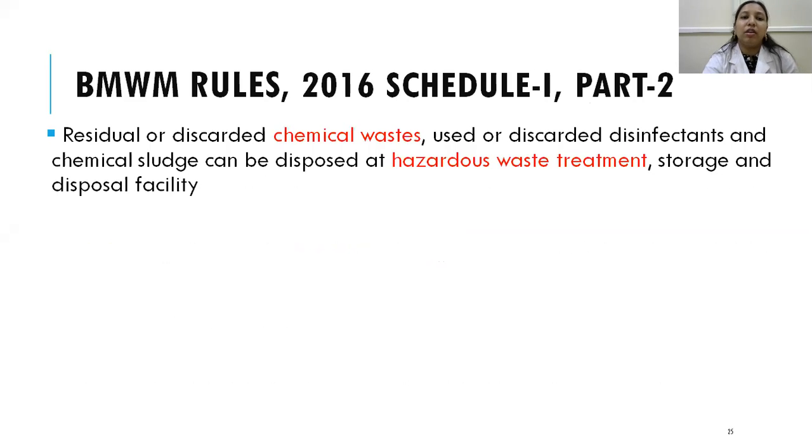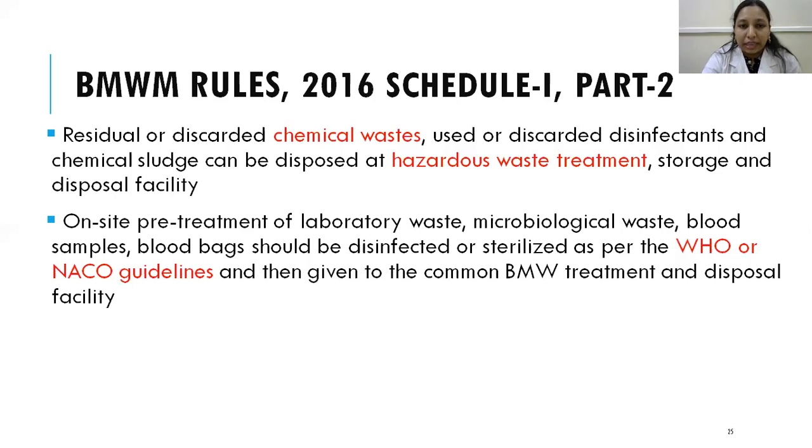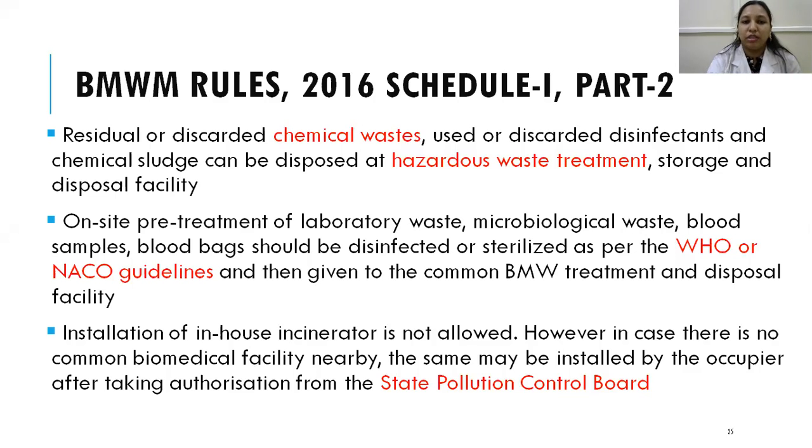The residual of discarded chemical waste, that is the disinfectants and the chemical sludge, can be disposed of at a hazardous waste management facility. On-site pre-treatment of laboratory microbiological waste should be done with disinfection as per WHO or NACO. What is NACO? National AIDS Control Organization. According to those guidelines, we have to pre-treat it, and then send it for the biomedical waste treatment facility.